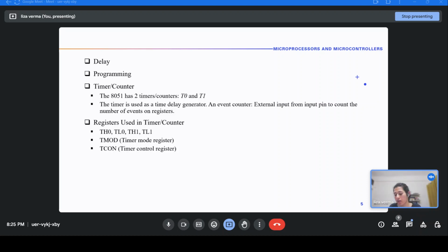And one more distinction. The way we use this software delay to put NOP in loop, what do we do? Initialize a counter number, and it will count down to 0, right? But the timers T1 and T0 are count up timers. Remember the expression? So they count upwards.